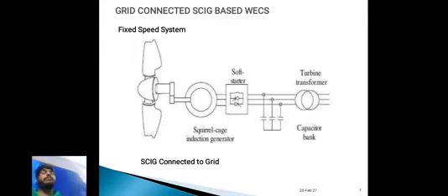The soft starter's purpose is to supply three-phase motor voltage gradually during the startup phase. It adjusts the machine to the load behavior. Mechanical operating equipment accelerates smoothly. This lengthens service life, improves operating behavior, and smooths the workflows.